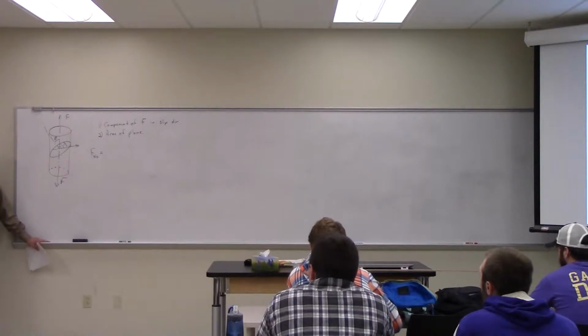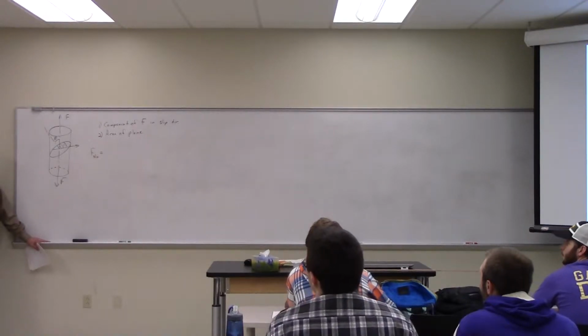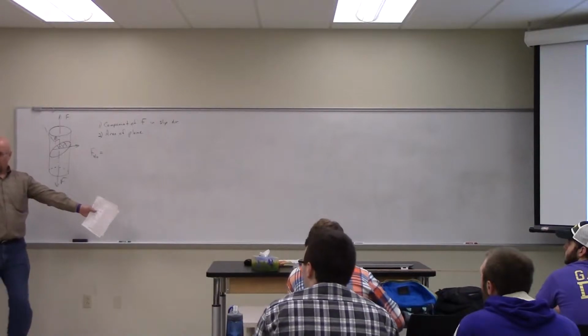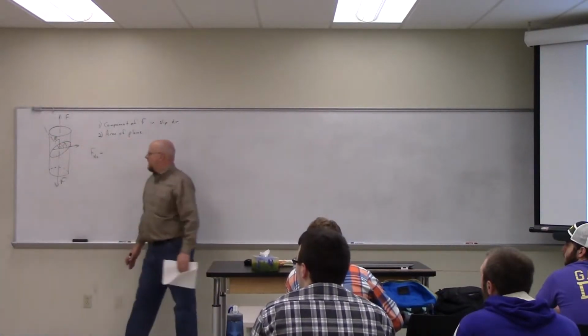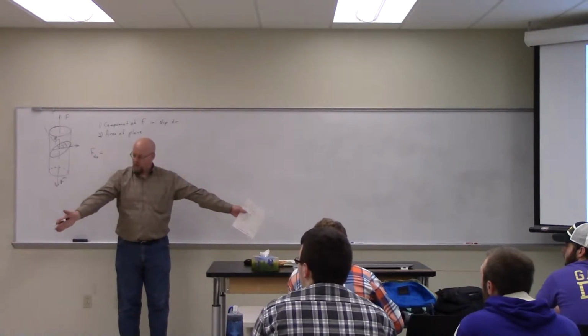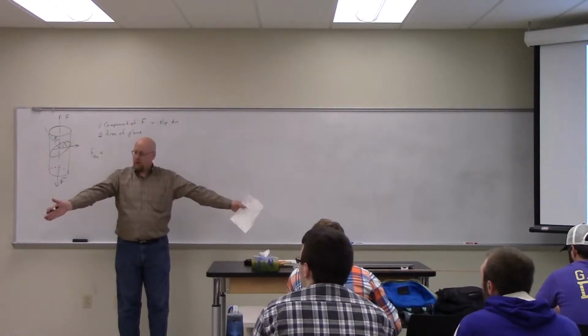How are those not the same if they're perpendicular? Because phi and lambda are not complementary. They do not add to 90 degrees. Phi is coming down over here, lambda is coming down over here. The normal and the slip direction are perpendicular to each other, but phi and lambda are not in the plane.